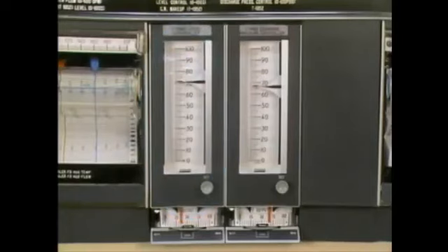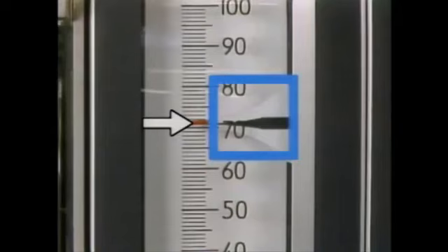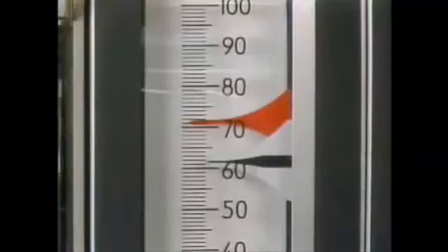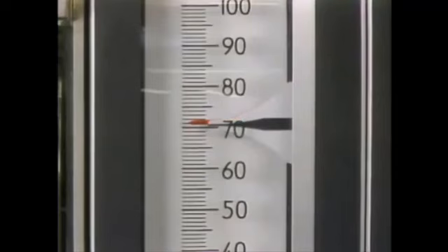However, for a smooth transfer back to auto from manual, the value of the process variable and the value of set point should be the same. Otherwise, rapid shifts in control action called bumps can occur. Bumps can adversely affect process operations, and they can sometimes damage equipment. To avoid bumps, the values of the process variable and set point should be equalized before a switch is made from manual to auto.